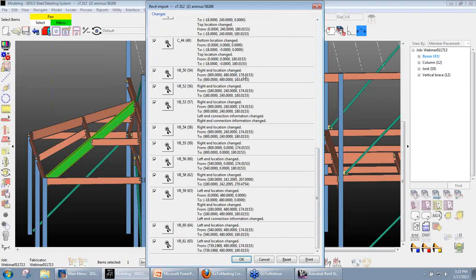So it's exporting all structural elements is what I did, and now it's trying to make that change back, or basically undo that change and sync everything up so everything gets back into sync and both models match up again. I don't want it to change those back, so I'm just going to go ahead and simply uncheck that.